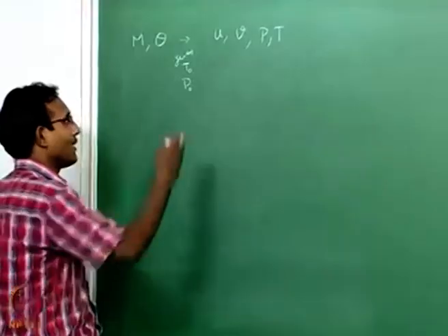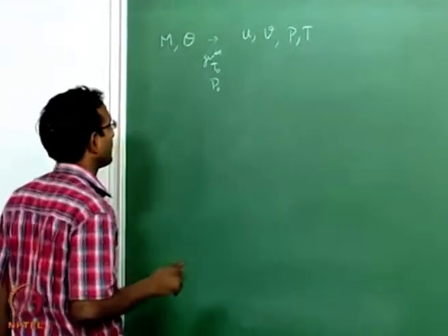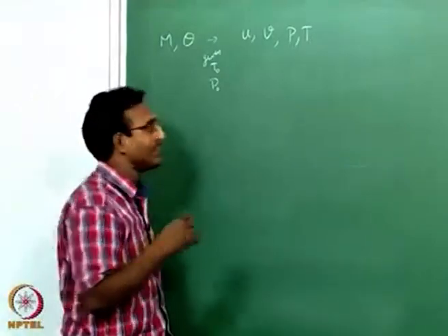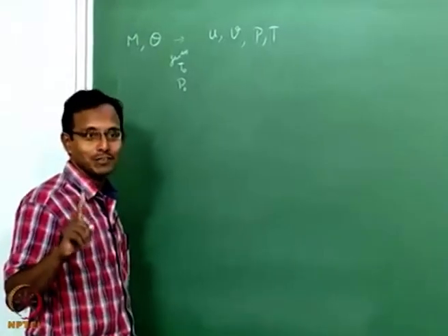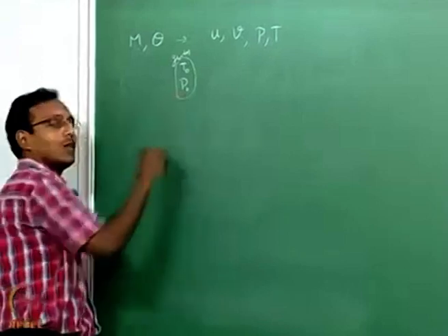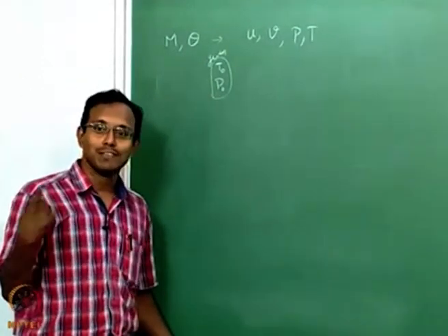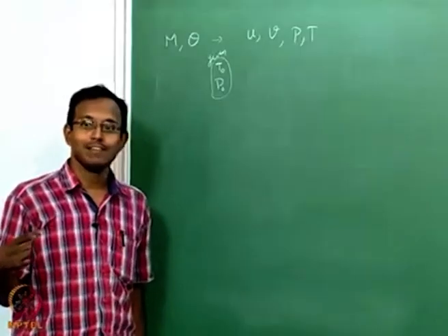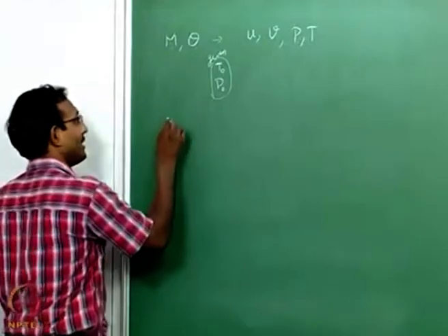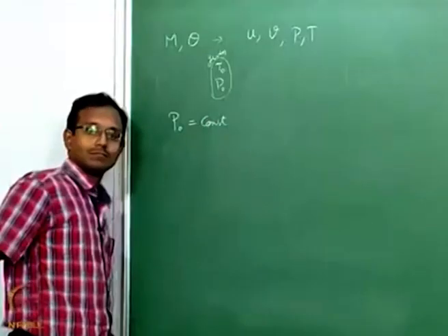Okay. So, now I can find density if I want, entropy if I want, all those can be obtained after this point. So, that is why we listed all the primary variables, and then we went in a particular direction where we ignored one equation, and that equation comes up finally here. How will I know P naught in my flow field? We assumed something about the flow. We assumed the flow to be isentropic, and because of that we know that P naught is a constant, right?